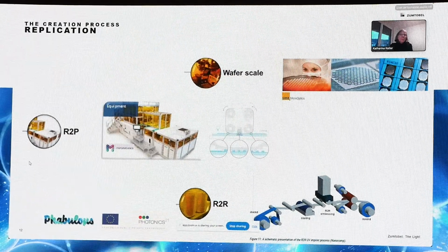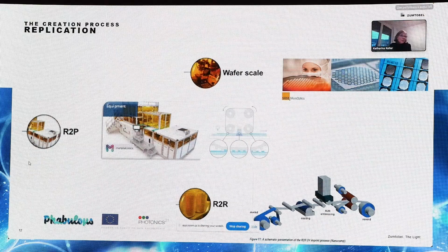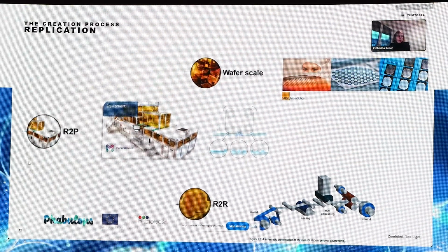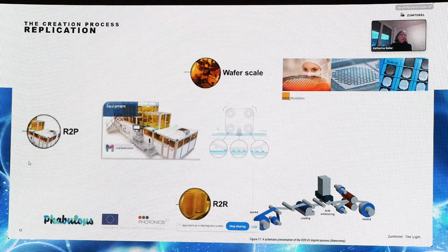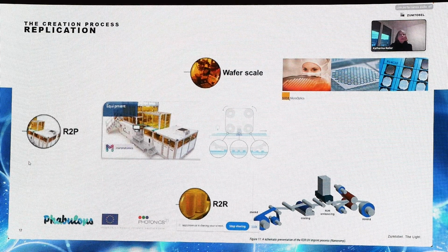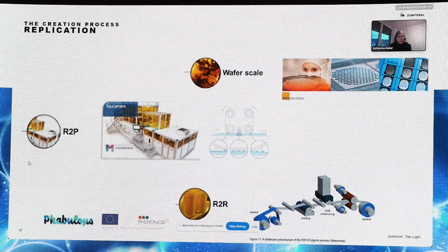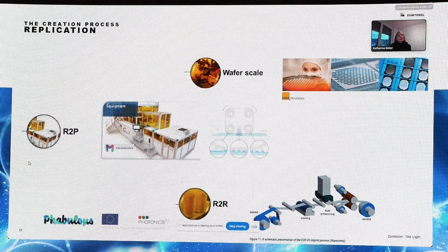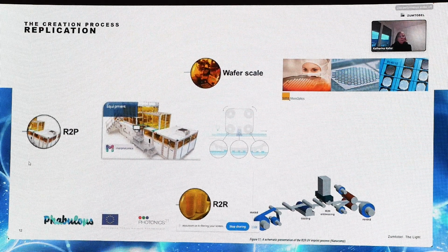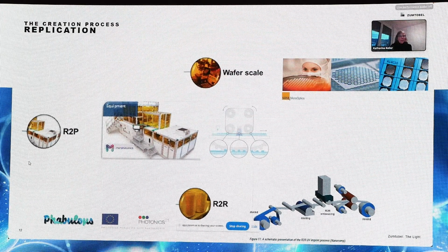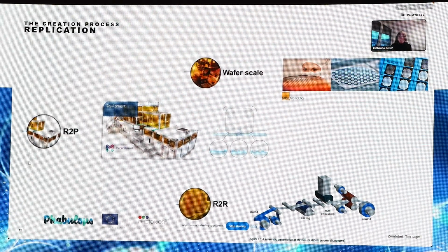The replication process, we have also heard before, all of them have in common that you disperse a lacquer onto a substrate, which can be film or rigid, like a plastic plate or a glass master. And then the replication is very precise in UV imprinting. In general you could also get it with other technologies, but UV imprinting is a technology which from its nature is very precise in the features.